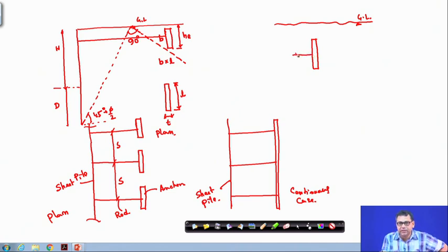Your force is applying in this direction, because your anchor is attached here, it tries to rotate. So you are applying force on this anchor, and the anchor will move in this direction. This portion of the soil is in active condition, this portion of the soil is in passive condition, because you are pulling this anchor, your anchor is getting a reaction. This is the anchor force. So that means this side is passive and this side is active.